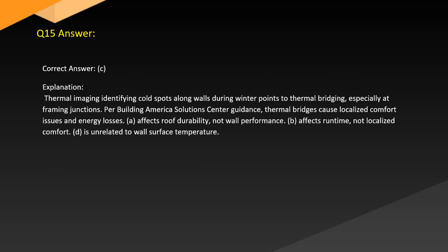Answer. Correct answer: C. Explanation. Thermal imaging identifying cold spots along walls during winter points to thermal bridging, especially at framing junctions. Per Building America Solution Center guidance, thermal bridges cause localized comfort issues and energy losses. A. Affects roof durability, not wall performance. B. Affects runtime, not localized comfort. D. Is unrelated to wall surface temperature.